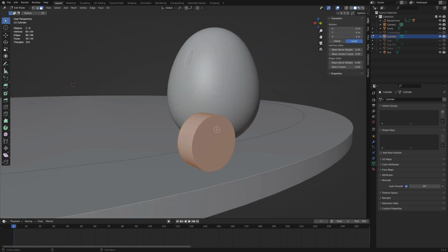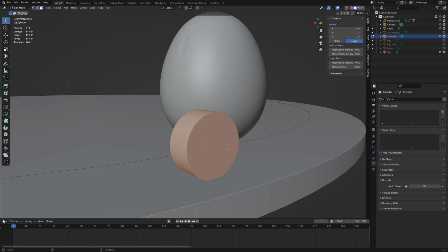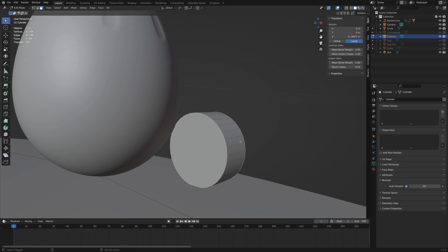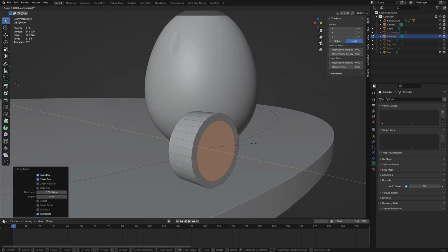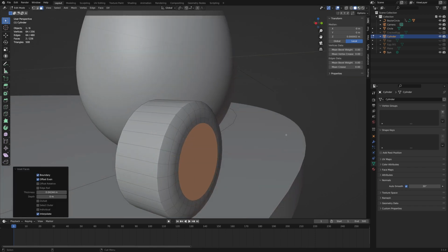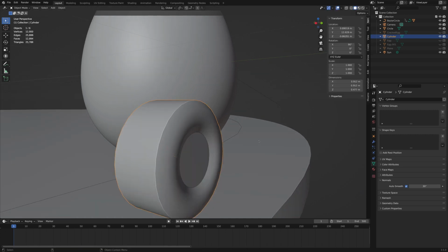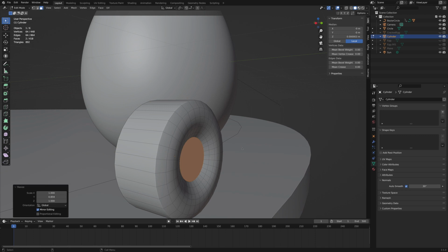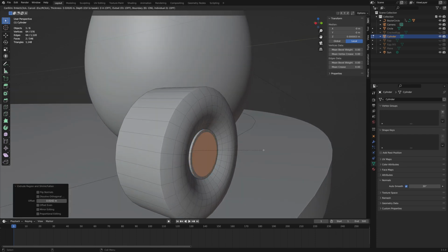And when you're done with the placement, jump into edit mode and we will model the tire a little bit. So we have a tire and a rim. I'm selecting both sides at once and using basic modeling techniques like I for insert, E for extrude, S to scale. And also extrude along normals, so it will be symmetrical on both sides.